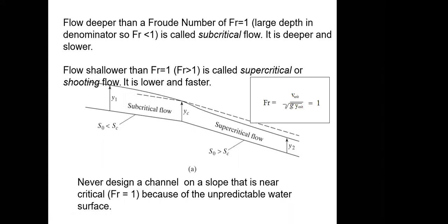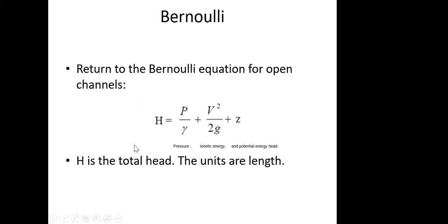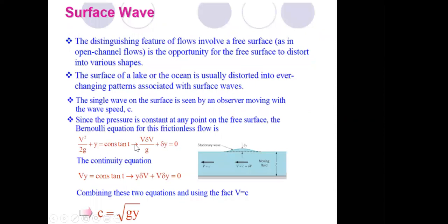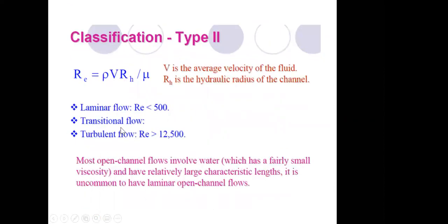Yes, it is. The characteristic length, or we call it the hydraulic radius, is a different thing. It's not only the perimeter. The Reynolds number over here that we use to classify laminar or transitional flow is not using L, but using the hydraulic radius.